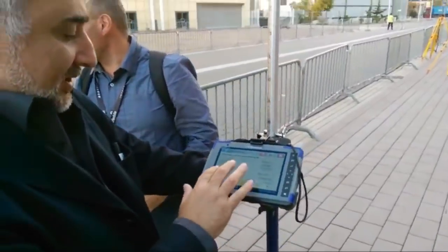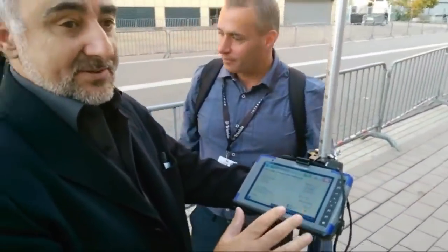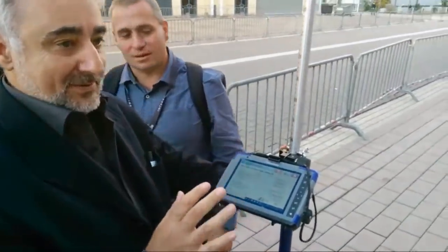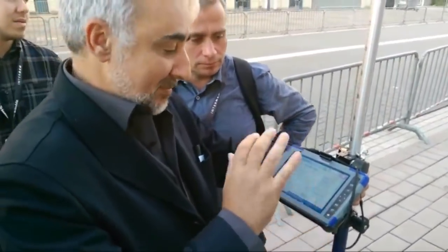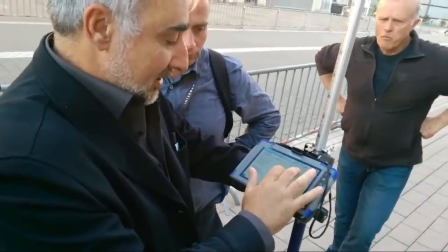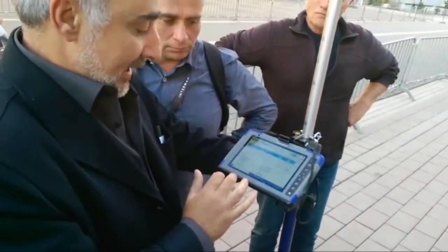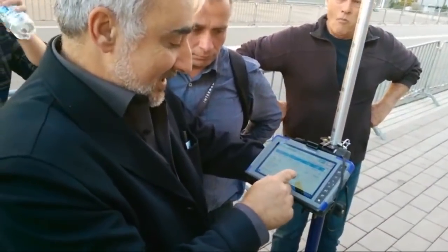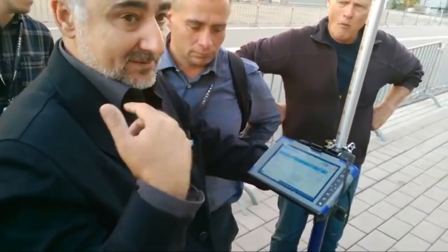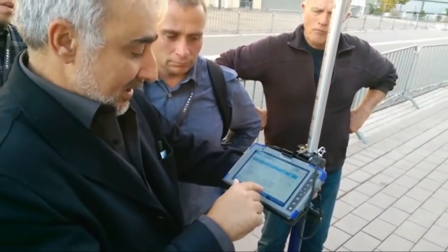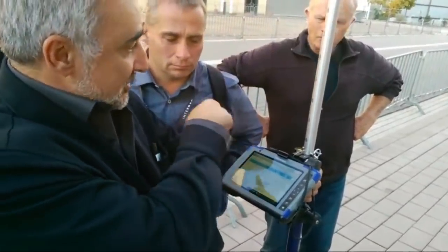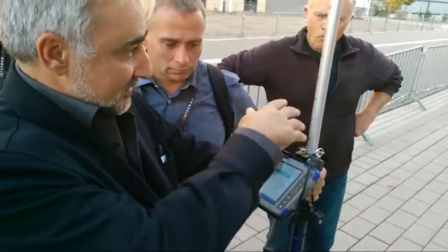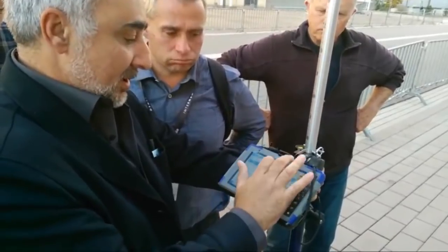So I did only a 3-point section, something easy and close, so not great precision, but believe me, it can be perfect. I calculated, and I got 7 and 10 millimeters in this bad situation, about 100 seconds. It's too much, but the GPS is not good. I was doing a short distance. We need a better place.